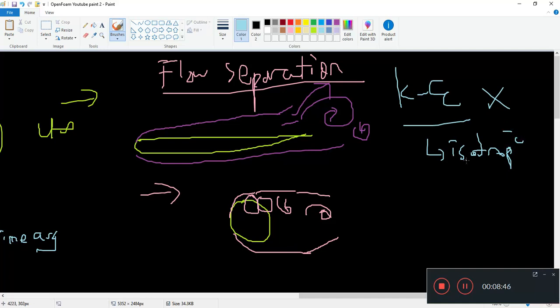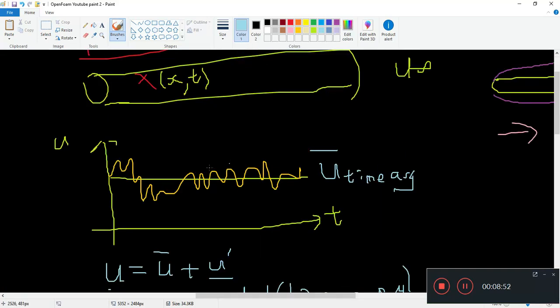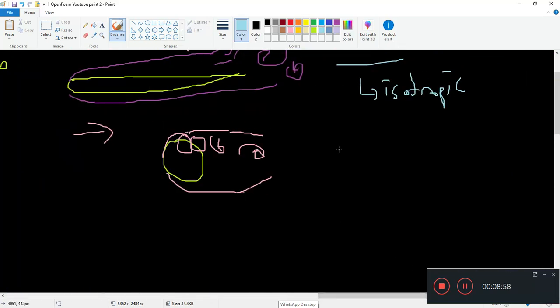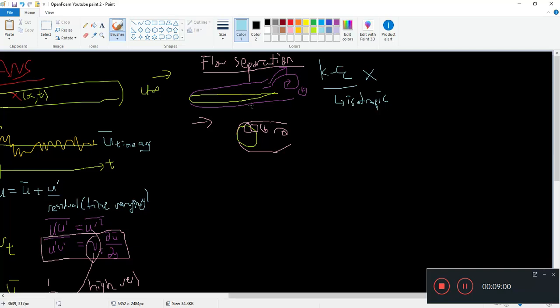because it assumes isotropic effects on turbulence, and it models all turbulence as increasing the apparent viscosity of the fluid in somewhat of a uniform manner. But that's not enough detail to examine something like this flow separation phenomenon.